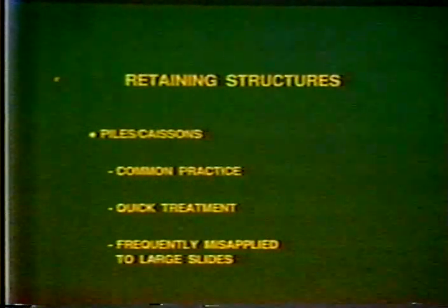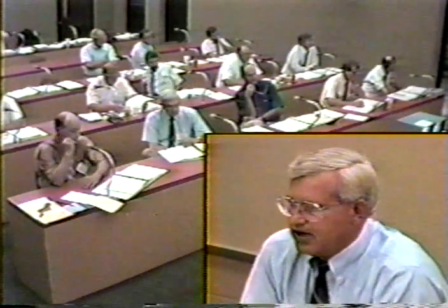It's frequently misapplied to large slides. It perhaps can be used for slides up to about 20 feet in height, but when you start getting into much larger landslides, you're going to get into trouble most likely, because you've got to remember that a pile system like this, if it's steel, is a very flexible, thin diaphragm that you're trying to use to hold back maybe a large mass of material.